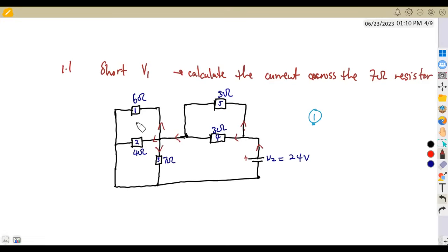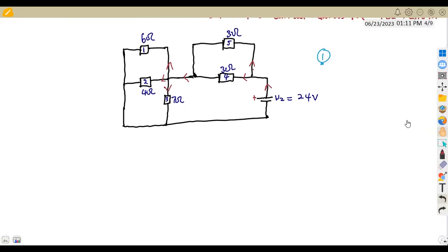So let us combine this into a parallel, this into a parallel. All right, so that's a parallel and parallel combination that we have. Remember in parallel that the total resistance in a parallel circuit is given as the product over the sum. So we're going to apply the product over the sum concept. So let us start with the first one. This one, I'm going to have as the first parallel combination.